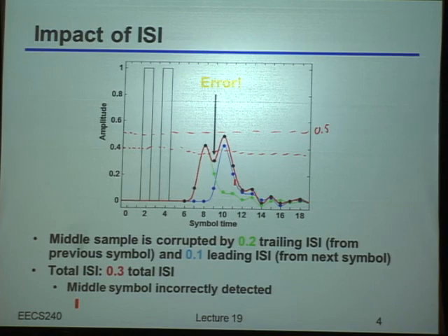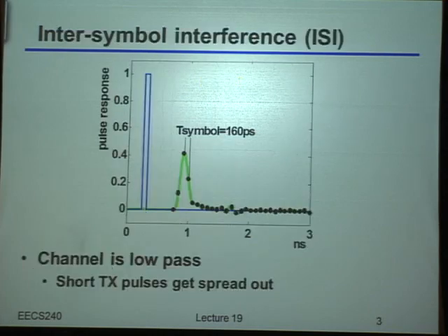Well, it seems like if you put it at 0.5, even without intersymbol interference, you still get outcomes, because if you just looked at, say, the green signal, that's all. Yeah, okay, but here's a little bit of a subtlety with this picture. Notice because everything is not center biased, what's happening here is that, in reality, the easiest way to think about this is that a 1 would be something that adds a pulse from 0 to 1, and a 0 would actually be a pulse from 0 to minus 1.